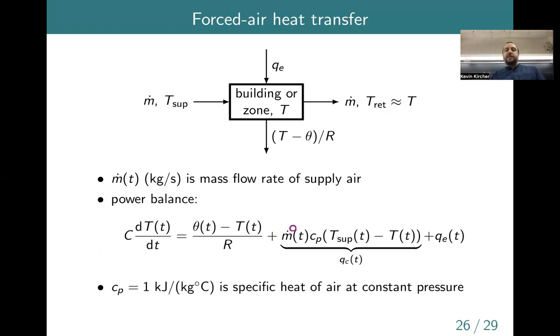So, questions about that? Okay. So anyway, this m dot C delta T thing shows up all the time in HVAC engineering. It's usually the way that we estimate things like heat transfer for cooling or for heating: we look at flows and we look at temperature differences, multiply them, throw a specific heat in there, and you get energy, basically.